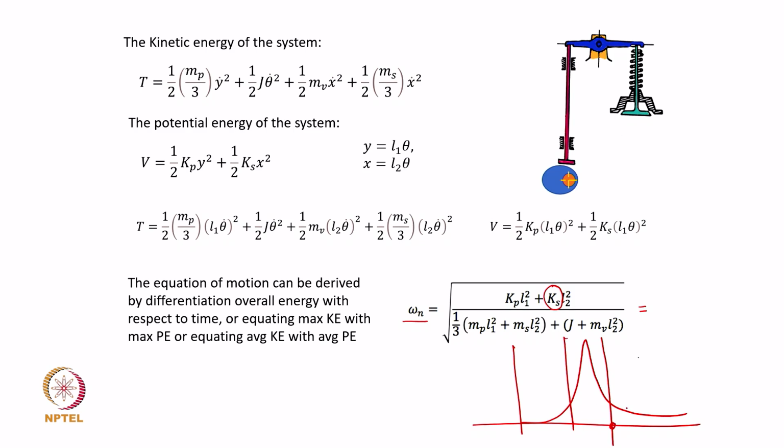Now, we have seen that if the engine operates at 550 rpm at its idling condition, the camshaft will operate at 275 rpm, and it is the camshaft that is pushing this entire vibratory structure or exciting this vibratory system. So, for me the excitation frequency omega is going to be 275 rpm.